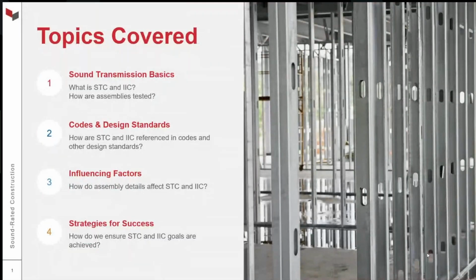I've got it broken down into 4 major topics. We're going to go through the sound transmission basics. What is STC? What is IIC? How are assemblies tested in the lab and in the field? I'll speak briefly about field testing and what that looks like. I'm going to show you some codes and standards, some design standards and code references where STC and IIC are mentioned and required.